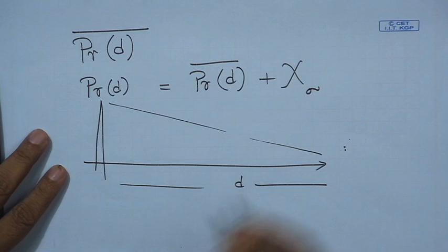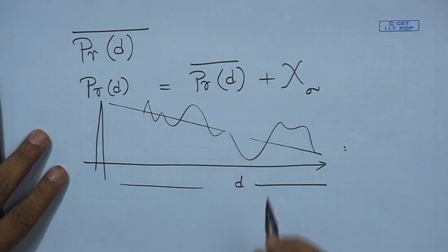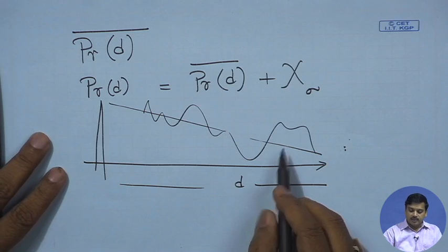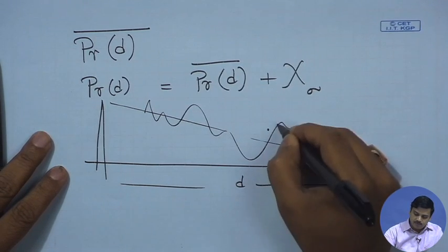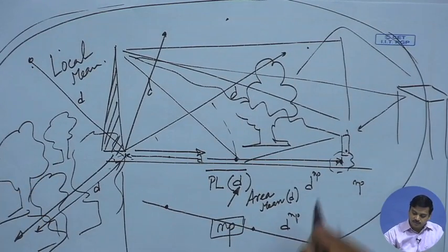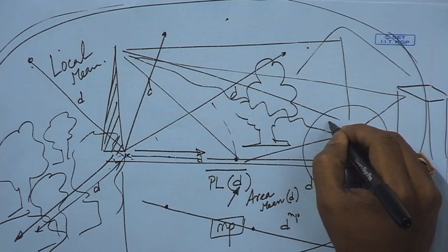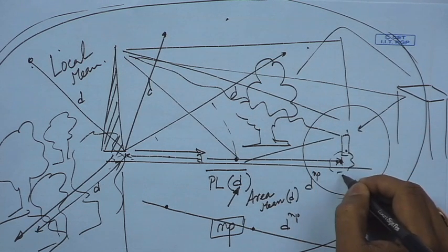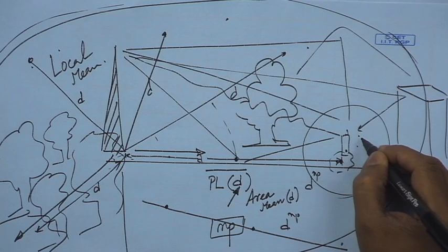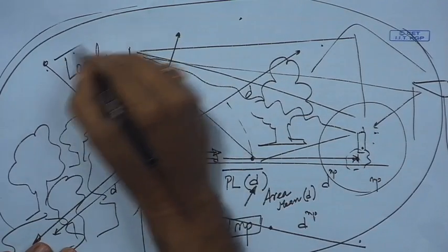there is path loss, there is shadowing. Now, this shadowing is typically correlated. That means we do not find abrupt fluctuations of average received signal strength. If we take this particular figure which we had drawn, in this region we would find slow fluctuation of the local mean. We would not find a sudden high of around 10 dB and within the next 1 meter another dB, because these are all averaging. This is the local mean.